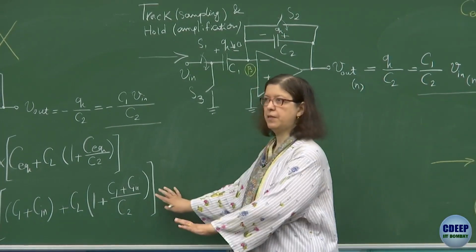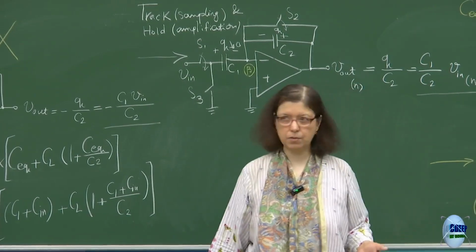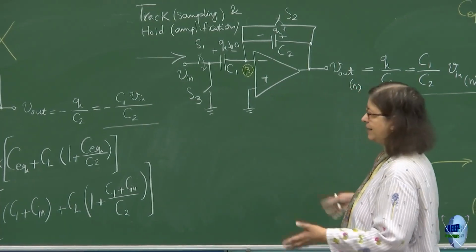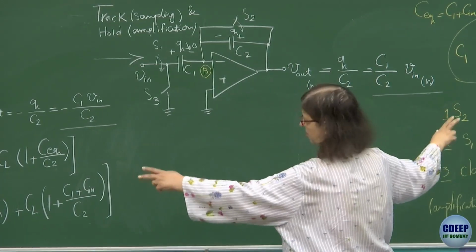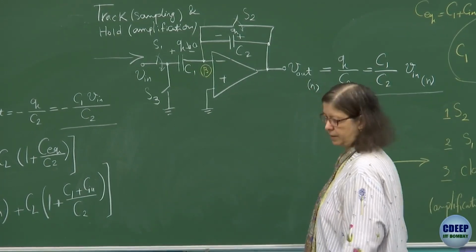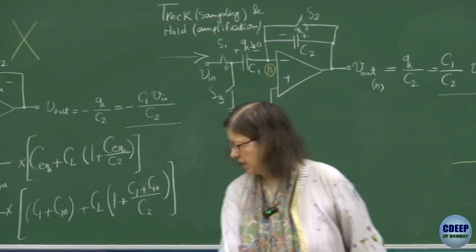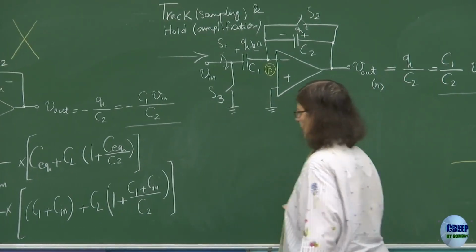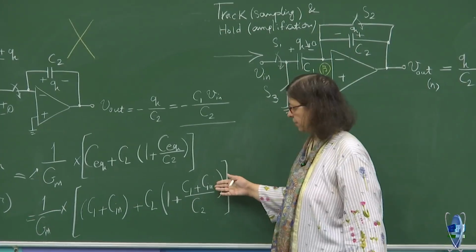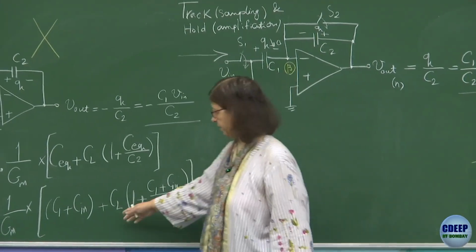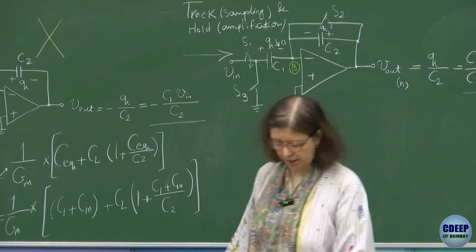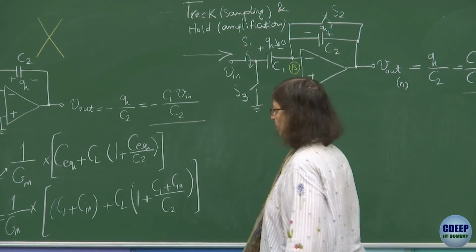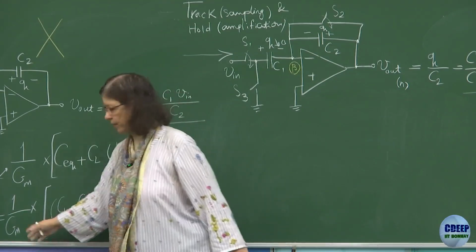Okay, so therefore, we don't really need to derive values or write the equations again. We are just going by the analogy with the two configurations, for the speed. So eventually at the end of the day, it's the same thing. Cin should not be very high. CL contributes to the speed, which is expected, right? And now finally, Gm, which shows the trade-off between the power and the speed.